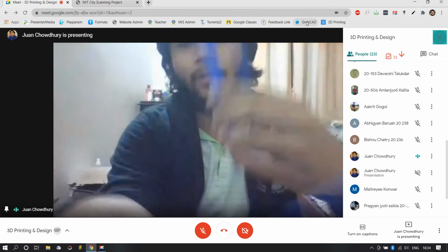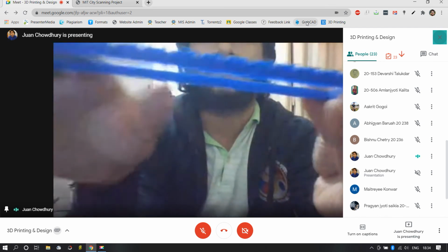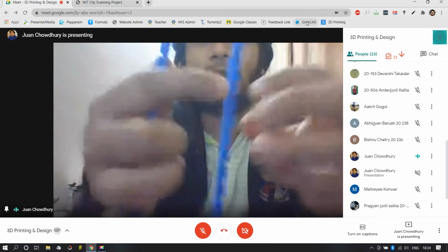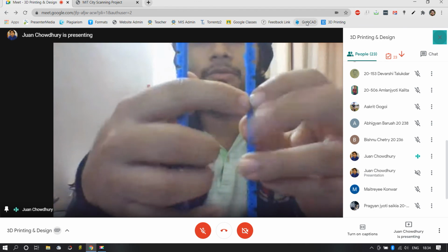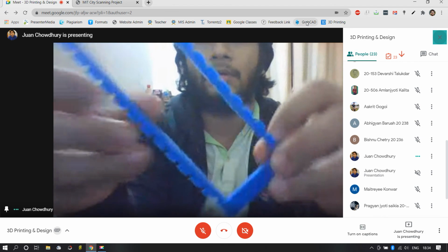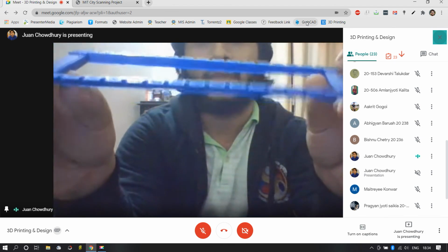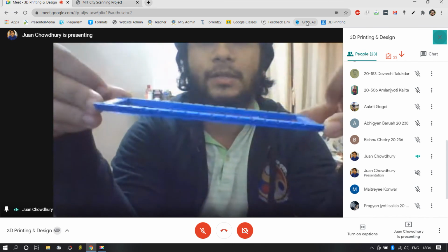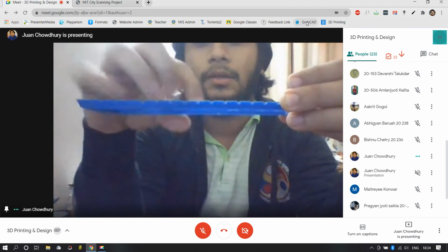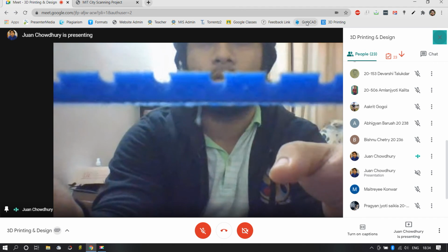Another problem is that if you have too many holes in the design, delamination of the surfaces takes place. If you do not have enough contact area for the layers to integrate, you will not be able to create the 3D printed parts as a whole. Okay, the most stable orientation was this, ground up, so it started printing this way, but there was apparent breakage of the layers within.